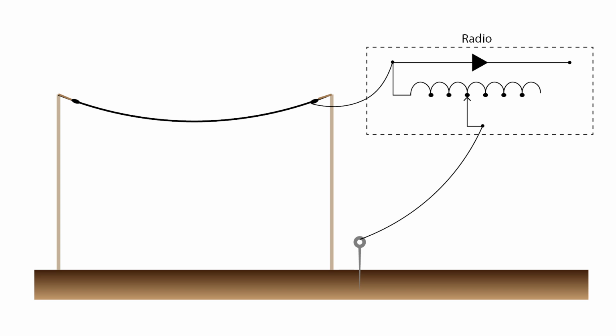The carrier frequency is still present. Well, fortunately, we can rely on our earpiece to take care of that. The earpiece is designed to respond to audio frequencies. Its physical construction means it can't oscillate fast enough to reproduce the carrier frequency. So in effect, the earpiece is acting as a filter, smoothing out the carrier frequency to leave us with just the original audio frequency.